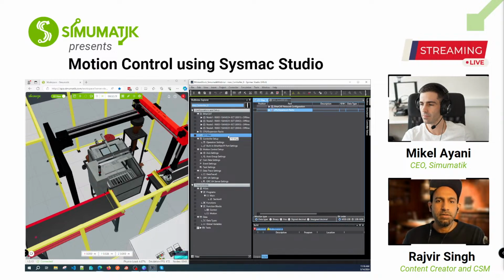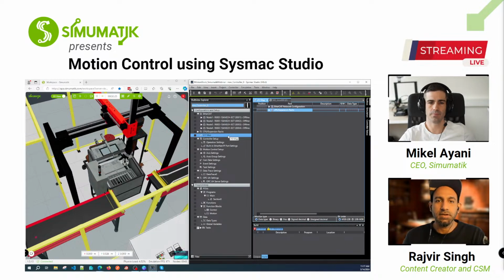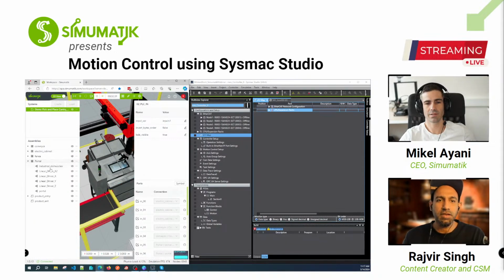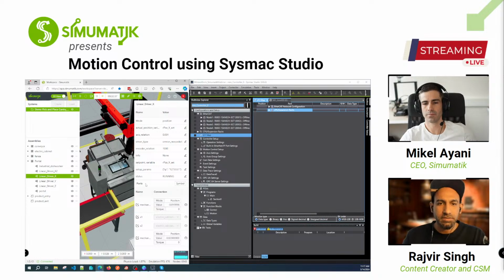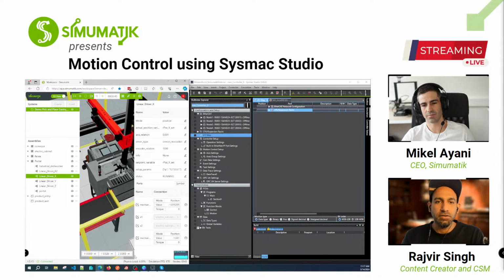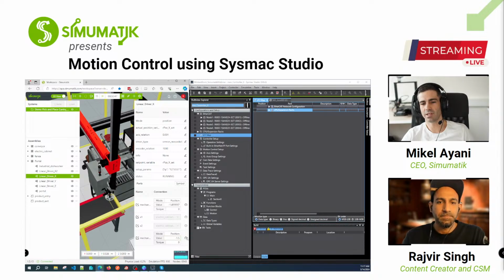And I would like to add that in Simumatik, we have some joint sensors which are sending the feedback value, and this we can use in Omron. Although we have a tiny example, maybe you can show in the end of this data trace, where I try to show the feedback. So you can also see it here, for example, for the x-axis. So it is getting the set point from Omron, and then Simumatik is giving a feedback, which we can use in the software. So we see here two values.